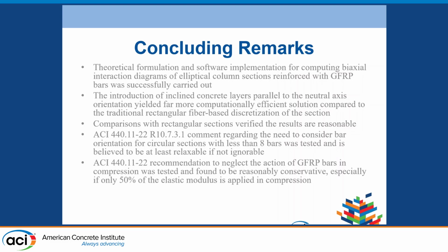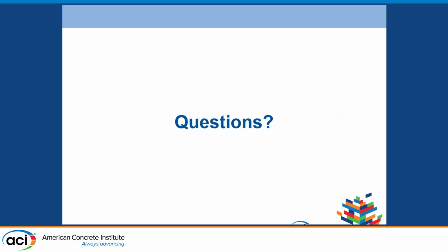And we tested the recommendation to neglect GFRP in compression, and we think, based on our results, that it's reasonably conservative to follow this ACI recommendation. And with this, I conclude my presentation.